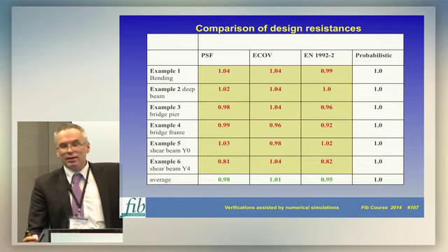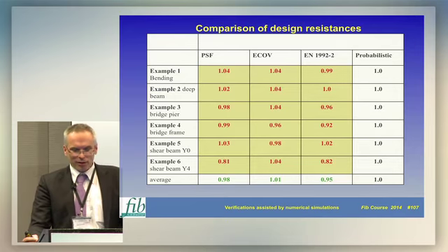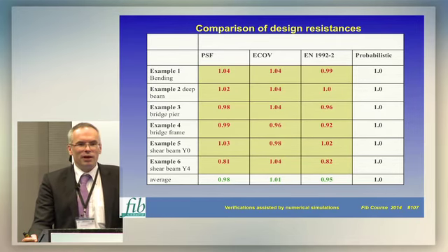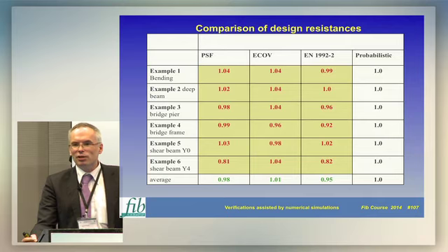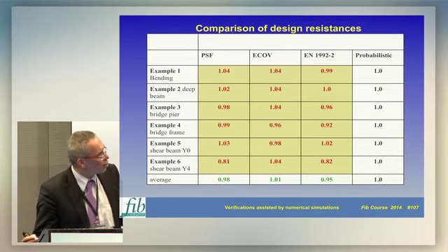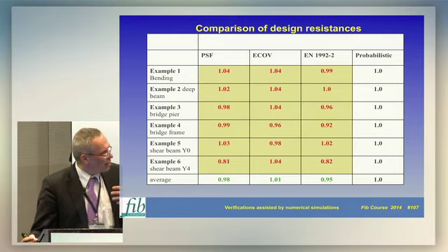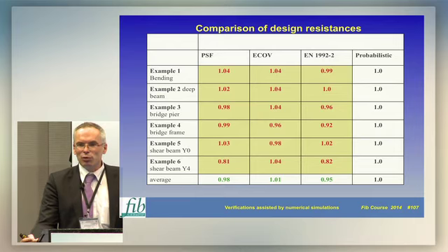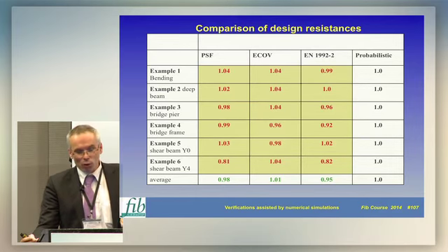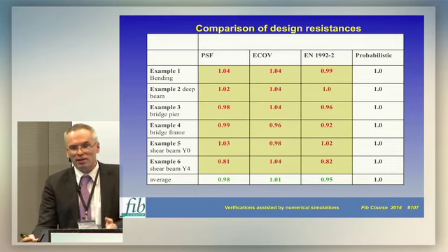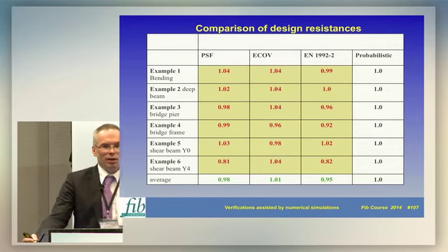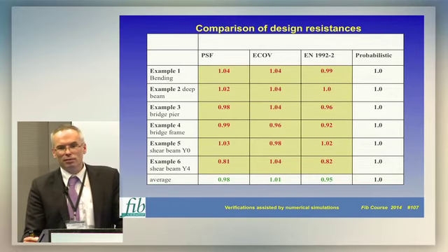So what we're looking at this, what was surprising to us is that there is no difference. I would say there is no difference, sort of. So there is, we cannot find any preference for either of these methods. So if there is no preference, I myself always saying, well, why then not use the simplest one and the most natural one, which would be to the engineers. And in my opinion, the most natural one to the engineers is the PSF method. The one where they make the nonlinear analysis using the partial safety factors.